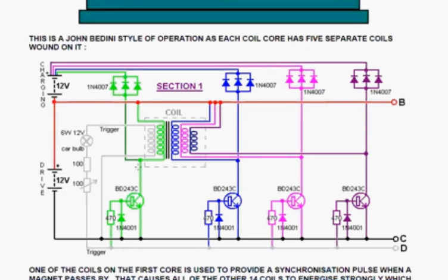But in actual fact, the way that you should do it is you take 3 diodes to lower the output impedance of the output flow of energy, and you feed each of those 3 diodes, the set of 3, back to the battery you're charging with its own separate wire. This is quite important. You want a low impedance on your diodes and a separate wire feeding the battery being charged. So here you see there are 4 separate wires going to the one battery being charged.